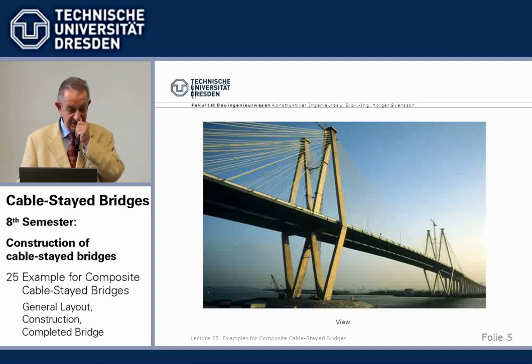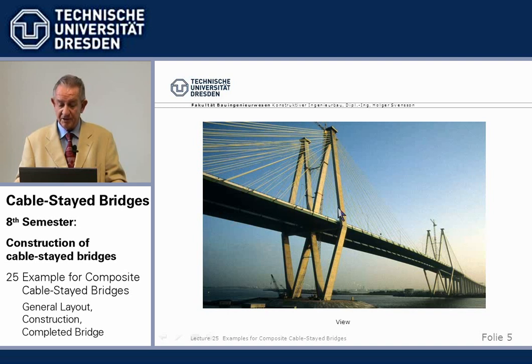Now, the towers then were a consequence of these 2 beams. We wanted 8 towers above deck for each beam for improved torsional stiffness. I told you about that. And then if we connect the two, we can also take the legs together to have only 2 foundations.